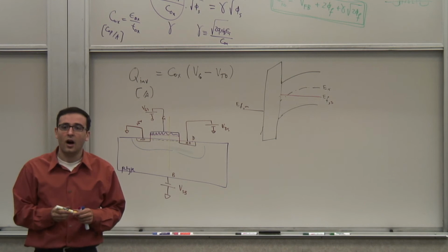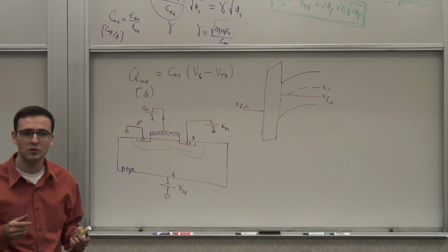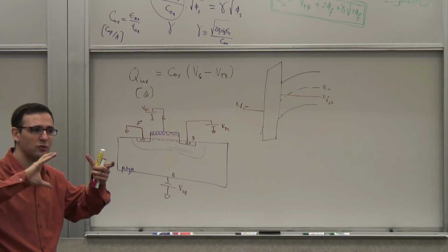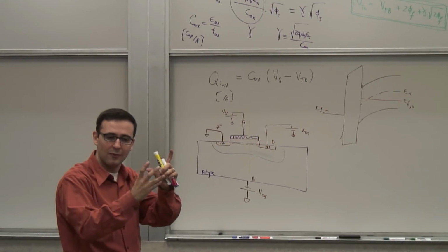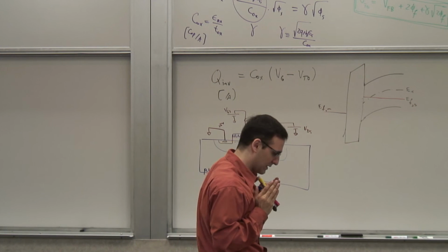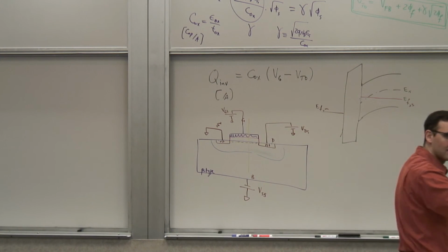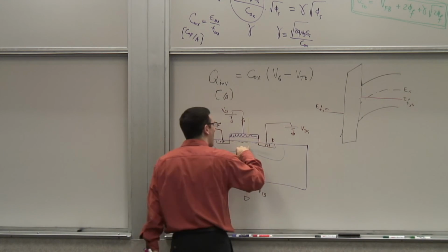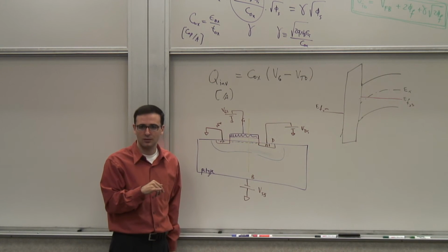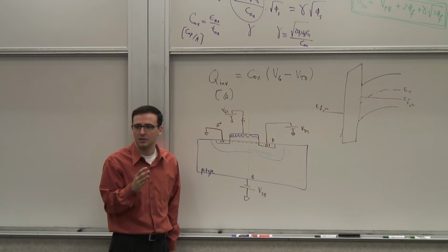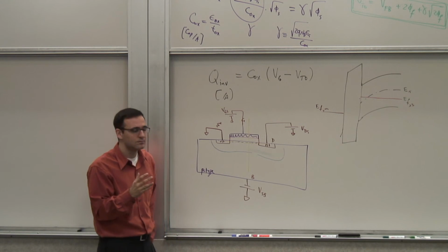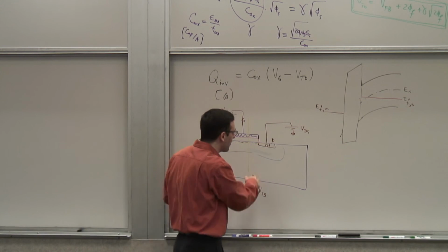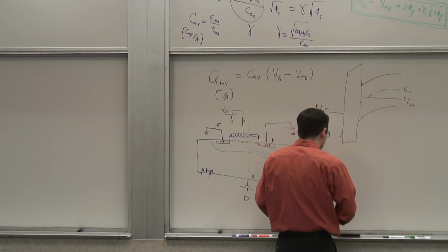And you can see, unlike the bipolar transistor, whose behavior could be predicted through a two-dimensional model, what we had was really a two-dimensional model, right? We didn't think about it, because we said, well, assume uniform current density across this rectangular design. But now here, I can't predict the behavior of this device with a two-dimensional model. I have to really think about it in three dimensions. So there's an extra dimension. Now I can look at the energy band diagram along this axis, and let's do that right here.